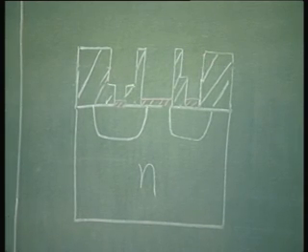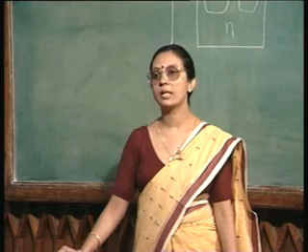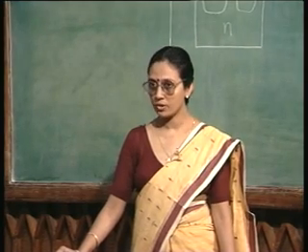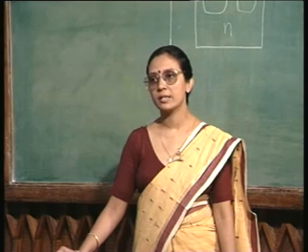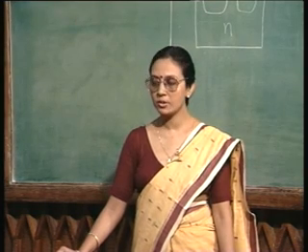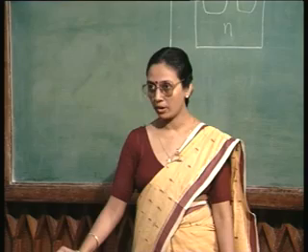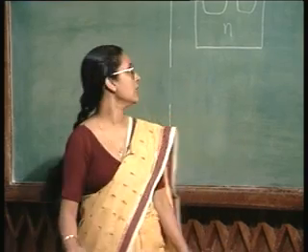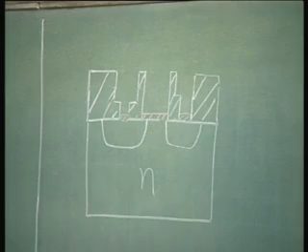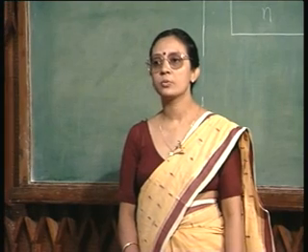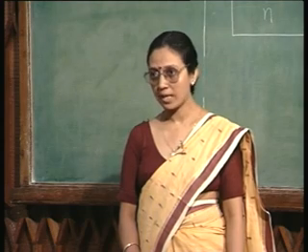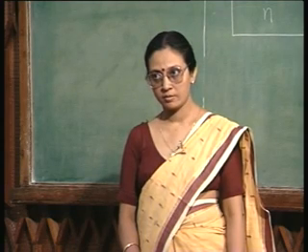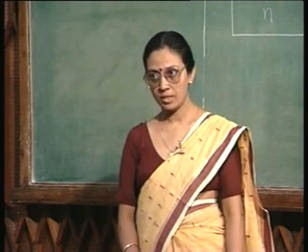And in the final step, once you have realized your gate oxide, your job is almost done, and in the final step all you have to do is to realize the metal contacts. So, the metal must be on top of your gate oxide, that will be the gate contact, and it should be in contact with silicon in source and drain region. Okay?